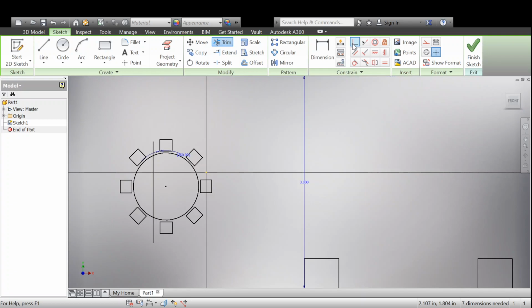Constraints point to other geometries. A point can slide with the curve, can slide and lie anywhere along the curve, unless constrained by a dimension. So this is to keep the actual curve on a given point of another shape. If you were to move any part of it, the curve would move along the center of the circle here.